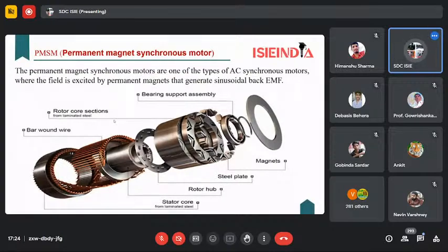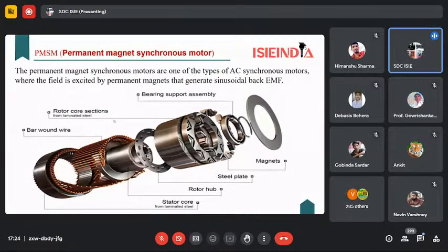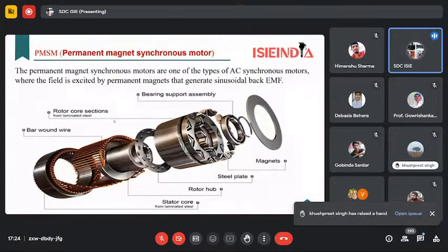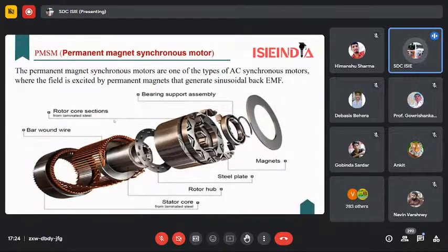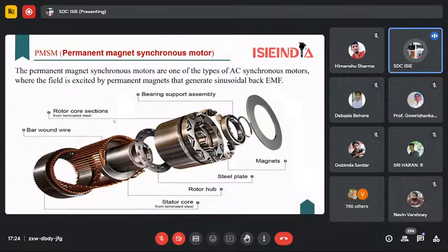A permanent magnet synchronous or AC motor consists of permanent magnets. It combines the best of both worlds, induction motors as well as the BLDC motor. They generate less rotor heat and are highly efficient. This motor generates a high initial torque as compared to a BLDC motor and has a more gradual torque curve through the wide operation range. So it provides a high initial torque, and while running, whatever the sudden acceleration, it will cover it. So we are preferring this nowadays, in the Nexon EV Max also.